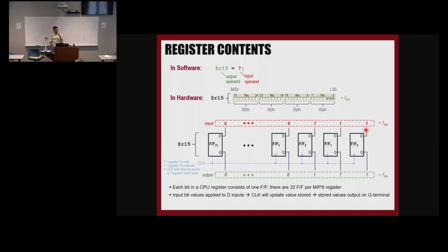It involves, I think the best design that you can get, probably 12 transistors, I don't remember exactly, but SRAM cells, for example, they need 6 transistors. DRAMs, they have a capacitor that stores the value, and they need refreshing and everything. Okay, so they're pretty big, but they're really fast.